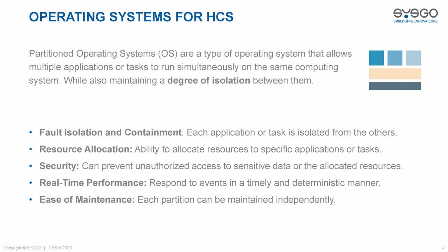In this context, resource allocation is the ability to allocate specific resources to those partitions. Those can be CPU cores, memory, input-output controllers, ranges of memory, which could be registers or RAM memory, but also time. It's important to take that into account. Security is allowing us the implementation of security policies specific to each partition.